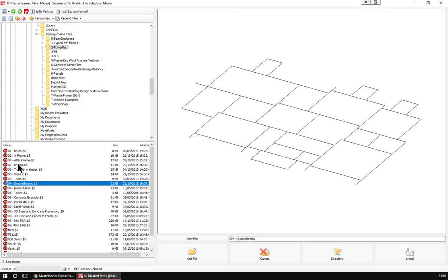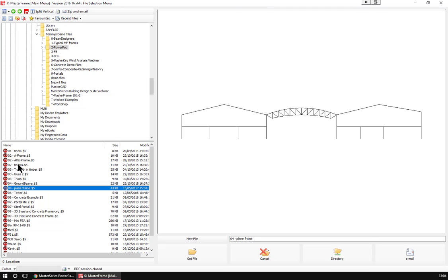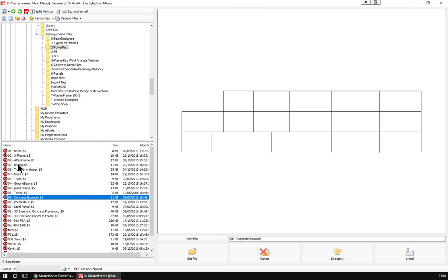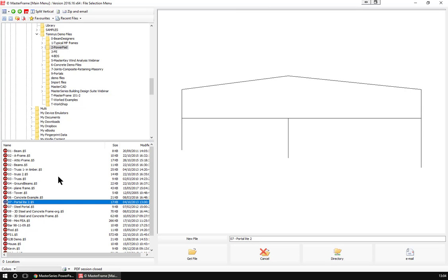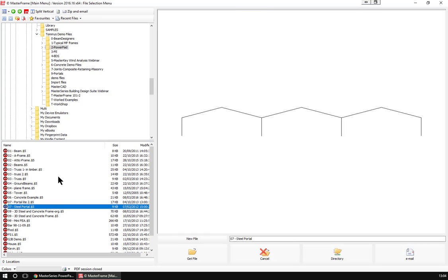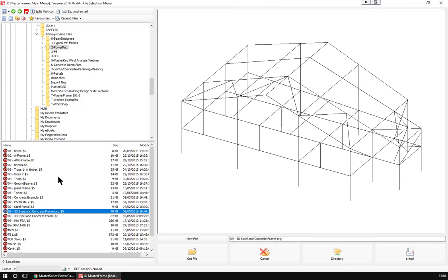So you have your A-frames, your trusses, very simple trusses, ground beams, concrete ground beams on piles with little cantilevers and continuous beams and the likes. Simple plain frames, uneven towers. A plain frame in concrete in this example, and you can see we would be designing those members as single spans, so compound, what we call super members. And even in the frame analysis we can do portals. And here's a 3D frame.